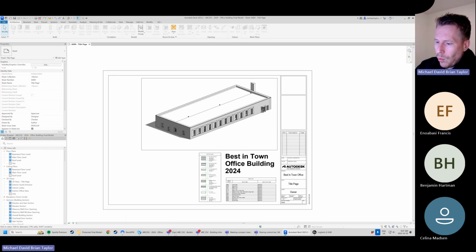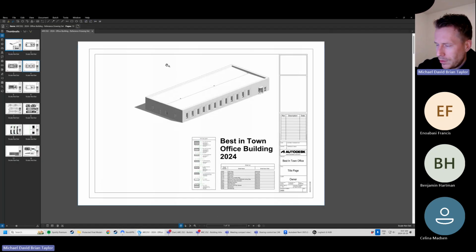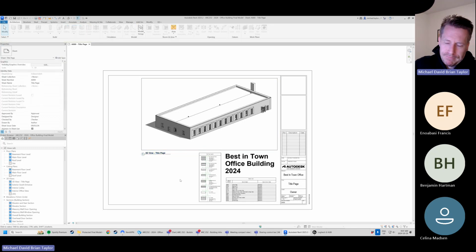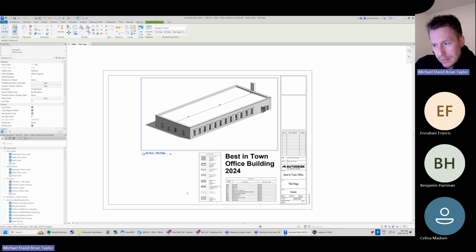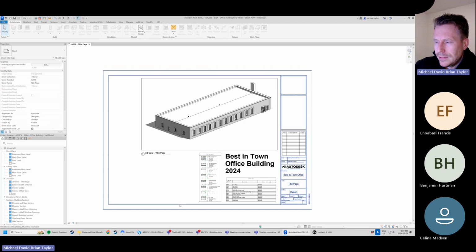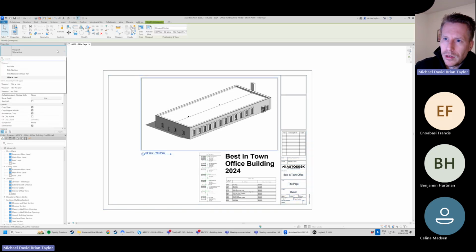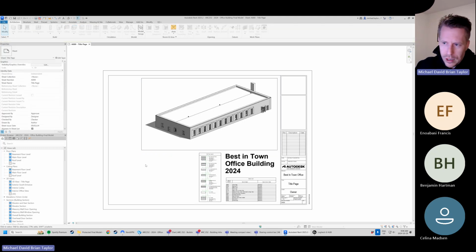So one thing we would see normally is just this first title page, right? We all know what a title page looks like, but this is for the contractor. It's for us, just to remember this is our project. So super minor thing. If we click on the view, a lot of us had this title no line or title with line. Like I said, I didn't take marks off for this. I just thought it might be helpful for us to see that if you don't want this little funny title here on our title view, we can actually just click on the view itself, come over here to the type selector tool, click the drop down, and hit no title, and it just disappears. It's not gone, it's just gone off of the drawing.